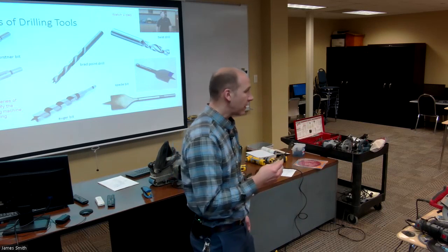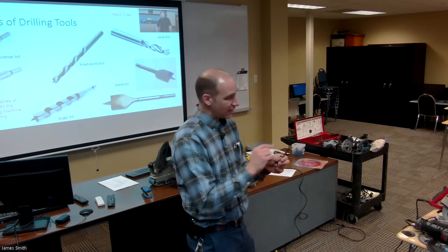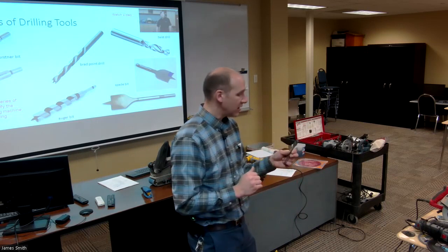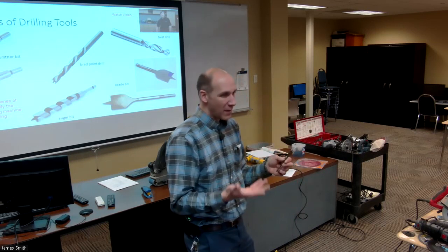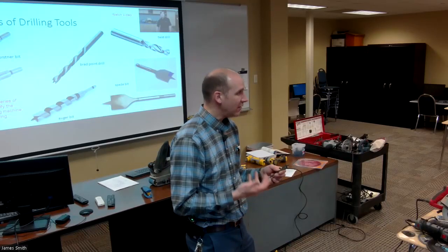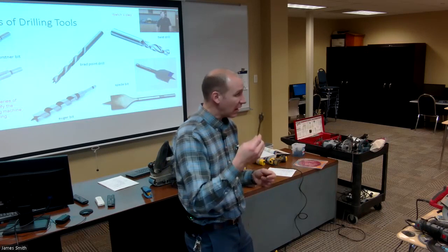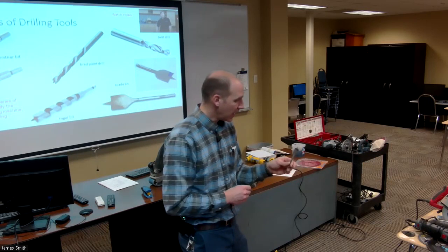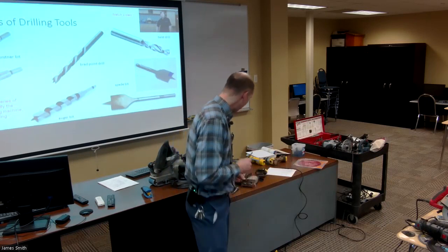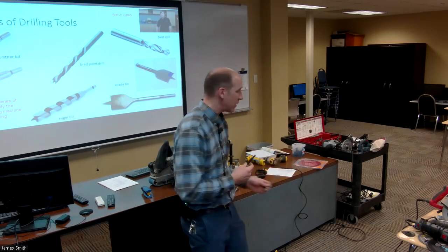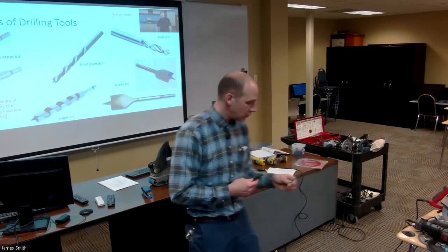If you're drilling through countertops, having a spade bit that has these spurs on the outside is good, but Formica, that melamine material, is really hard on tools, and so you don't really care when you use a spade bit because they're cheap. That's why I like using these for that purpose. But these will also work well if you're running wiring and you don't have one of those special auger bits. Something like this would do the job as well.